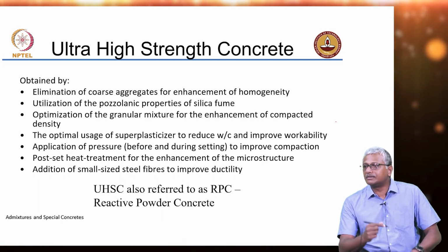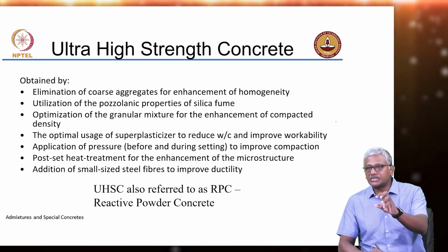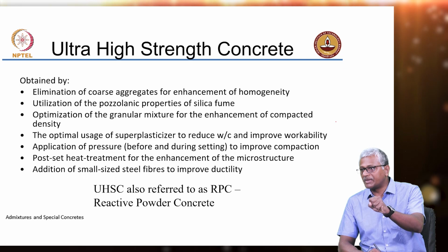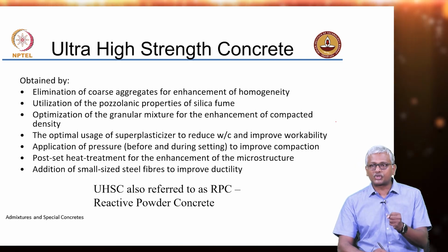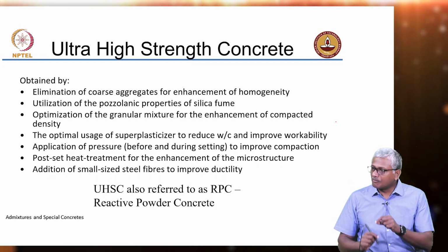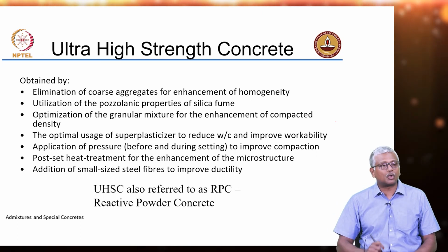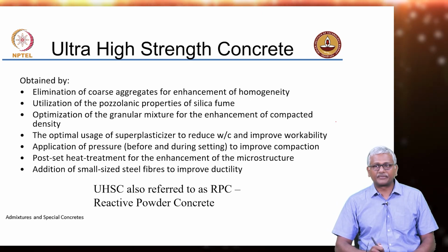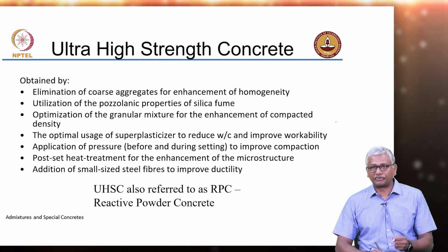I was saying earlier that when we shift from normal concrete to higher strength, we generally tend to reduce the aggregate sizes, because now the paste matrix and the ITZ have become so strong that the cracks tend to pass right through the aggregate. So if you have more aggregates on the way of the crack, the crack has to go through all those aggregates to really cause the failure. Okay. So that's why we want to make the concrete as homogeneous as possible.